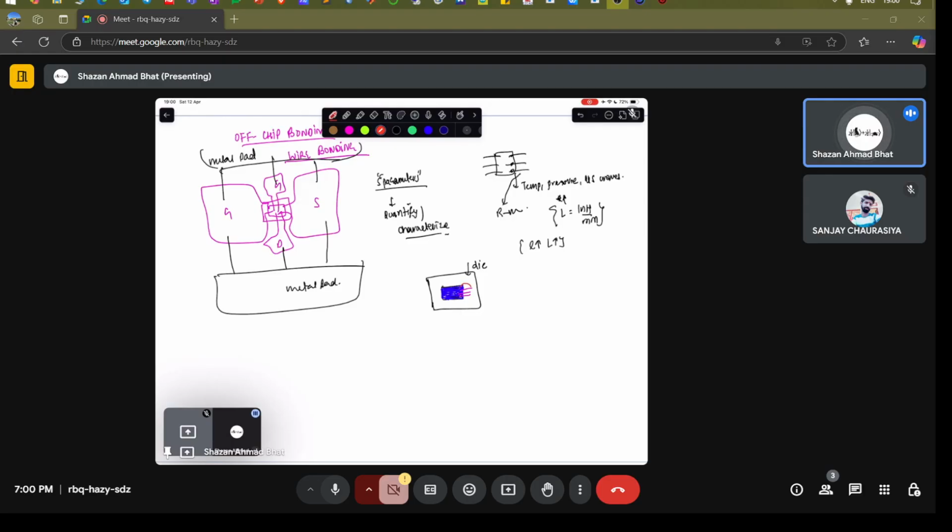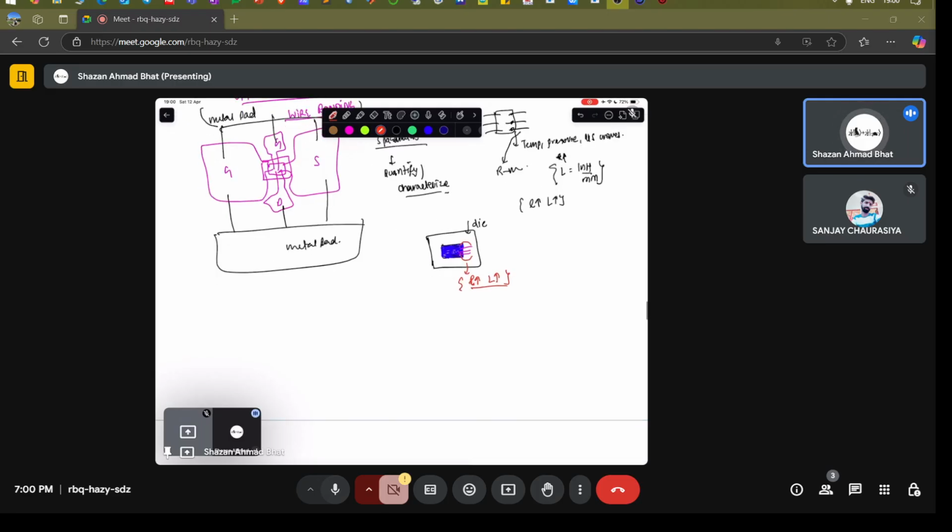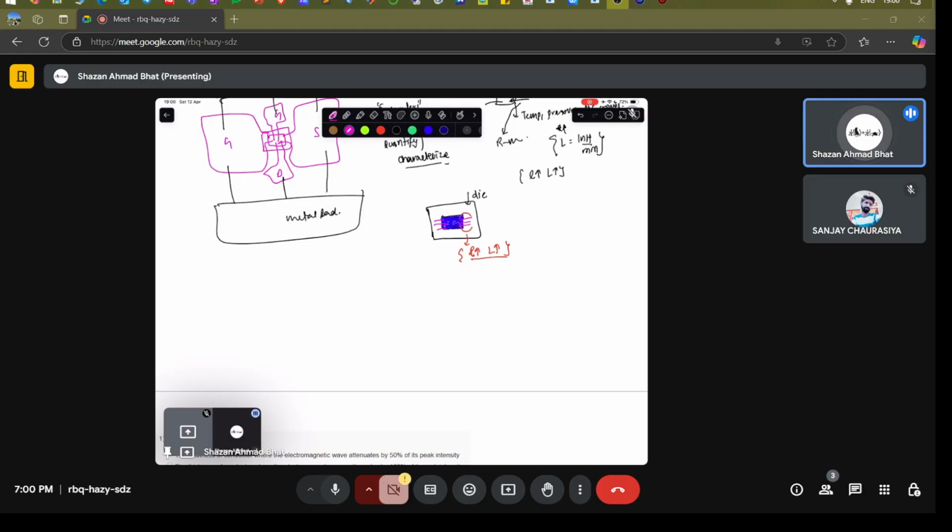Okay, if there is certain thickness out of the die, then they will make an arc, and if they make an arc, the length is going to increase and inductance is going to increase. Then they will be detrimental. So that's why you wanted it to be like this. The wire bonding wire should be exactly in the plane, and there should be no out of plane component of the chip when you place it in the die.